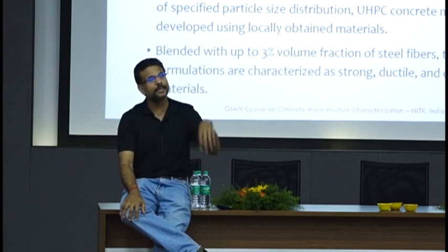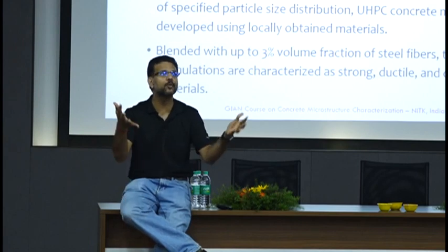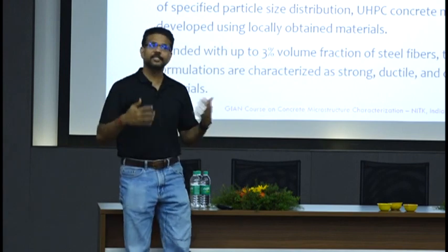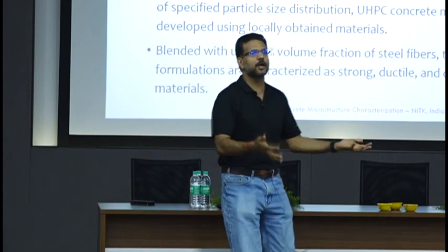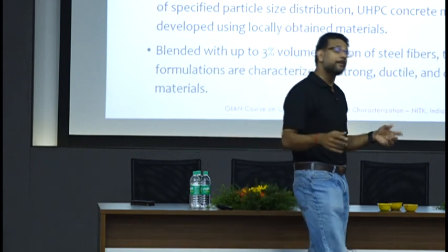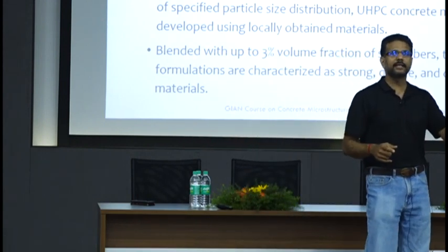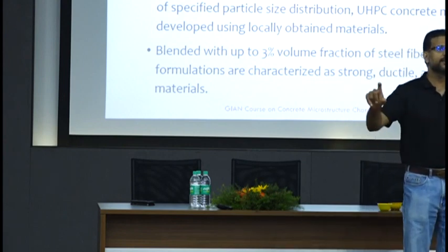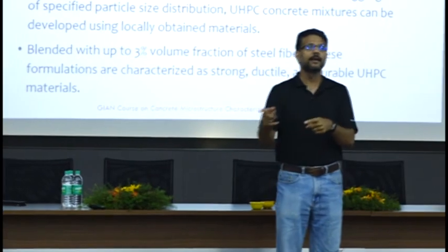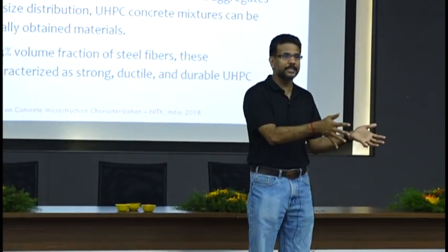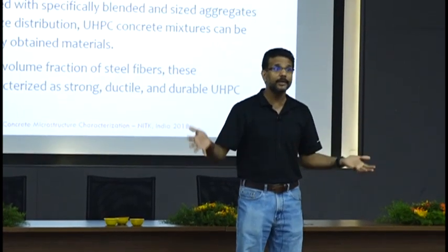Find out how much of the cement has reacted, how much of the fly ash has reacted, how much of the silica fume has reacted. That is quantified. And then you say that my fly ash reacted 20%. Just because fly ash reacted 20% does not mean fly ash contributed 20%. Right? There is absolutely no way to break that down. What people do is, oh, I'll compare this with an OPC where I have 50% fly ash, and based on some strength ratio, I say my fly ash contributes so much. Nonsense, because in a proper OPC, the physical and chemical reactions are totally different.